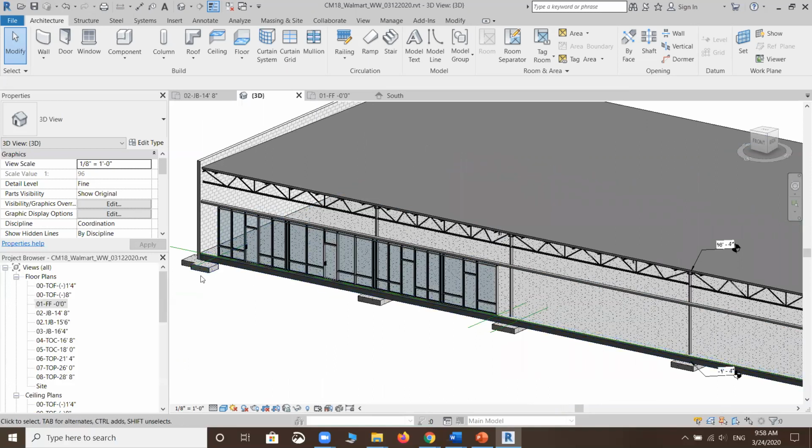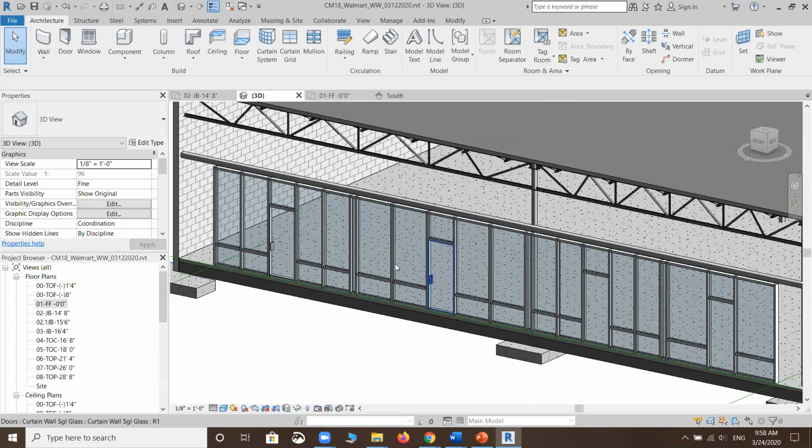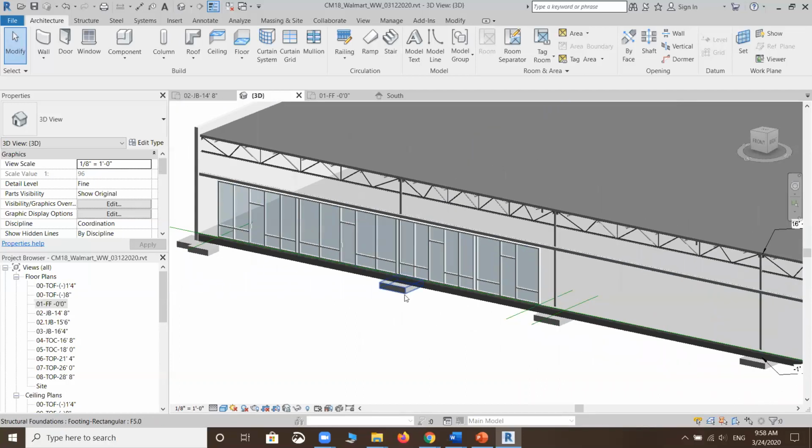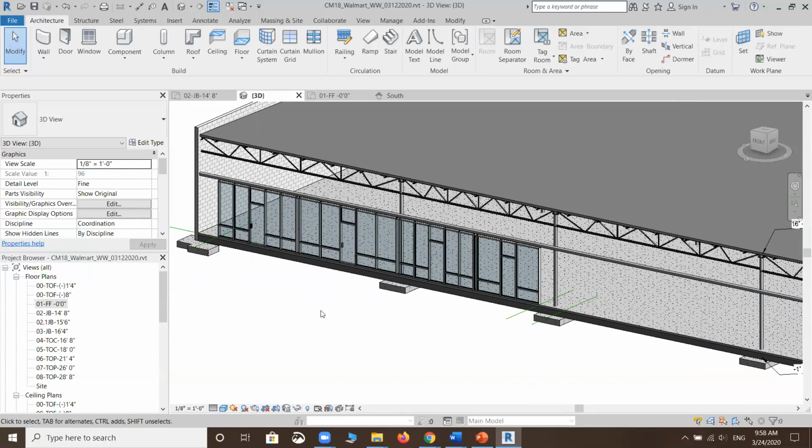We started by putting those reference lines, right, to locate where the curtain was supposed to be. Then we drew the piece of glass. Then we laid out the curtain grids to separate those panels into subsections. Then we applied the curtain mullions on top of the curtain grids. Then we placed the panels where it's supposed to be a door instead of a piece of glass, right? So any questions?